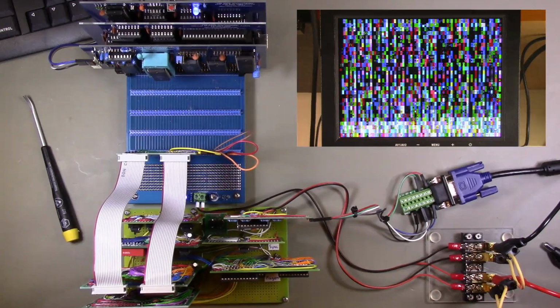I was super excited when I reached the point where I had a stable display. I was certainly a little worried that I wasn't going to get to the point where I was able to eliminate the glitches, and it was very gratifying that it turned out to be as easy as using 74ALS logic rather than 74ACT logic.